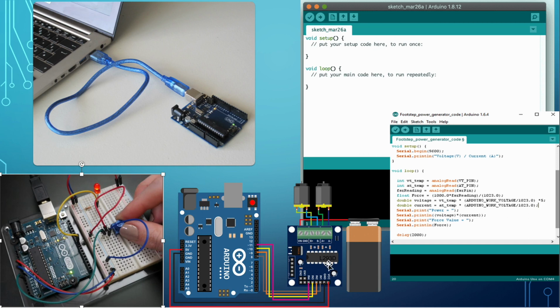So this is a physical visual representation of what you will see in an embedded IoT system, how it would work, right? When you build a project, this is the schematic of how the connectivity will take place. You can see the pins are being used, there is power given to the board, but because these are two motors, there is a separate battery unit giving power to the motors, because the Arduino board is not enough.